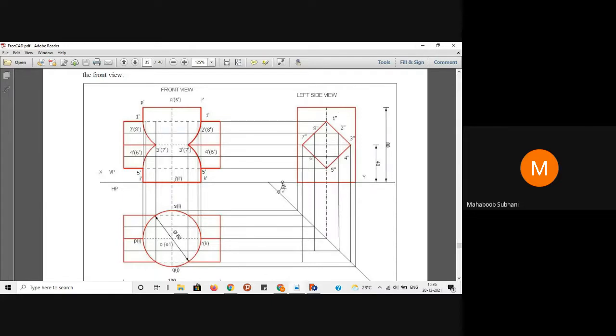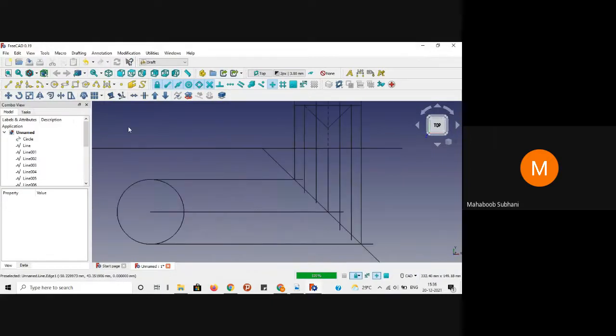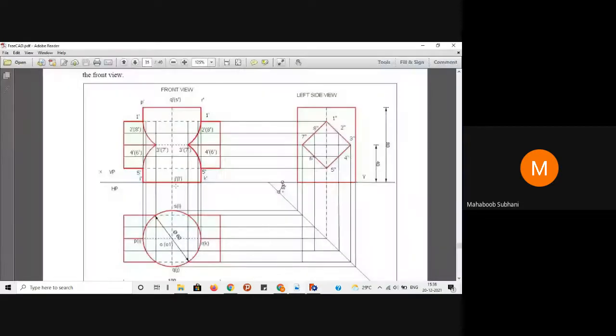Yeah. Now we have projected all the endpoints, the corner points and the midpoint, with reference to our 45-degree line. Now we project these same projections towards the left where we get the top view. So that we are going to do now. So already there are lines. Now, if you look here, the cylinder part is there, right? So that part will stop here.